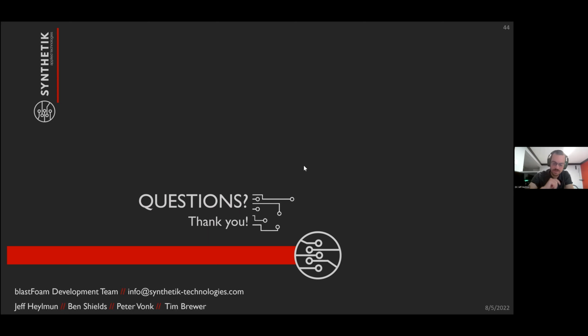We have SSP methods in there. That's Ruuth-Spiteri 2001, I think, and all of this is in the user guide too. We have the standard RK2 SSP method, and then we also have some higher step counts. I never recommend going over a Courant number of 1, but technically they're stable up to either 2 or 3.